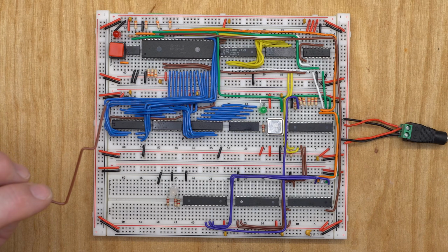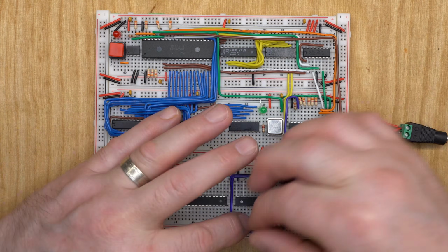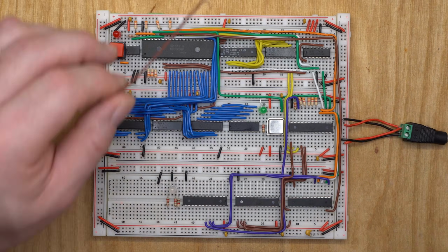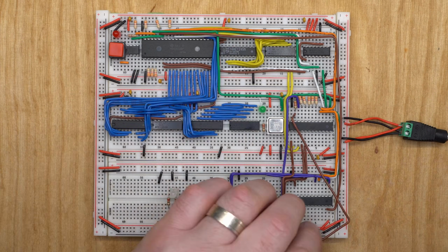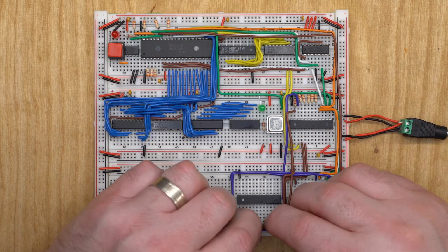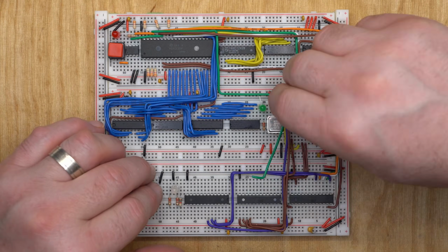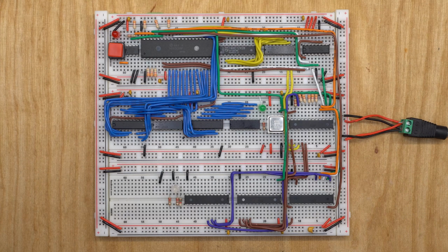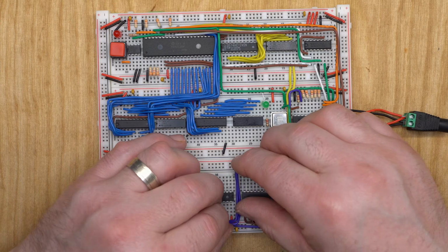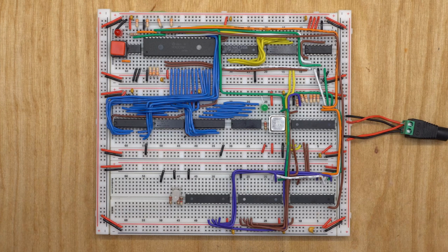For the wait state bus, WS0 and WS1 from I/O decode pins 15 and 16. Then to wait state gen pins 11 and 13. I/O decode also gets the oscillator output to pin 1, read-write to pin 3, and I/O request to memdecode pin 2.